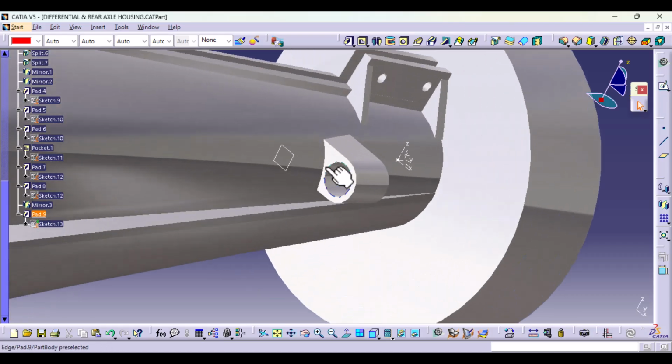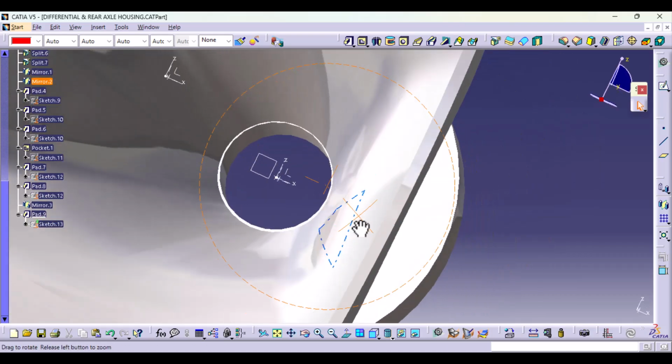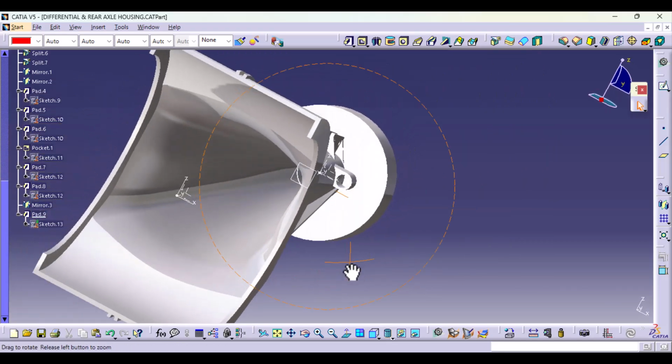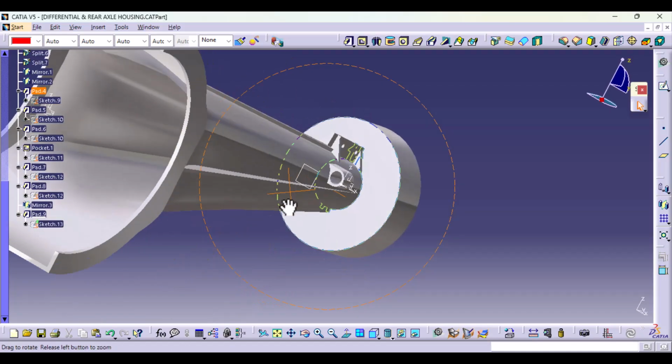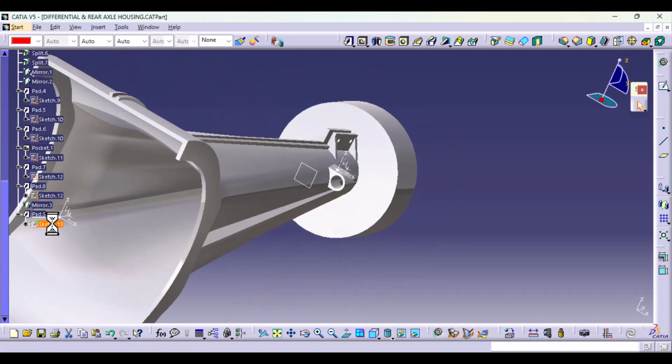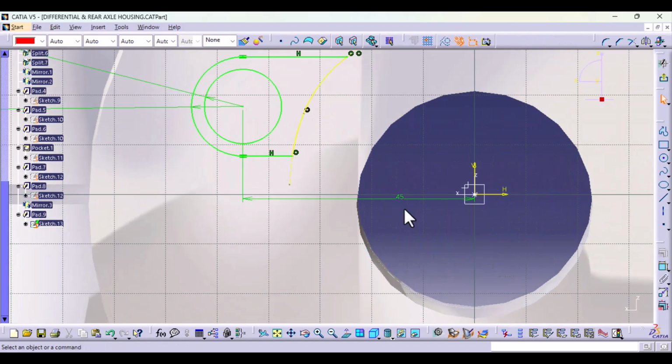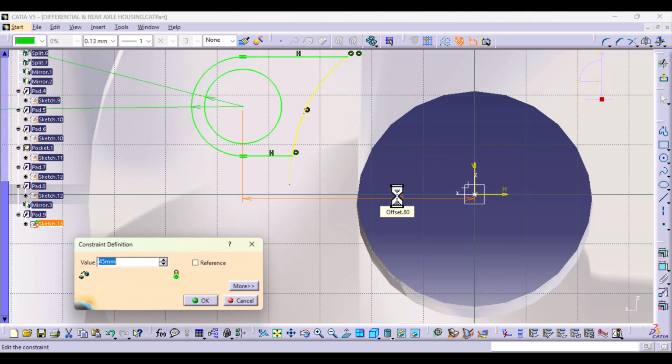I do want to leave a little bit of space, because when you're creating such a place, you want the spanner or whoever is attaching this bolt to not struggle a lot. So that distance from the center, we might have to add it. Let's add 10 millimeters. We did 45. Let's do 55.